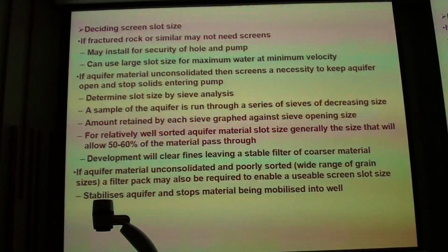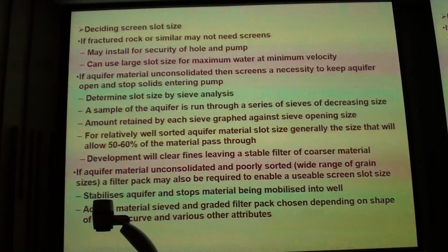The drillers will be able to give you a really good idea of what you need as well, because remember, often they've been doing this kind of thing for a long time, they've seen a lot of material, and they have a lot of experience with different types of aquifers, so they can have some input into how you construct your well. But you don't know that until you've drilled at least one hole.